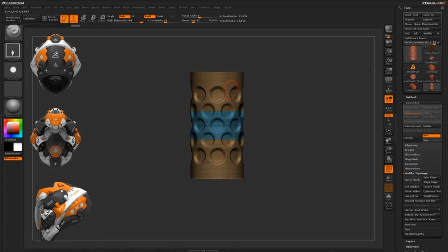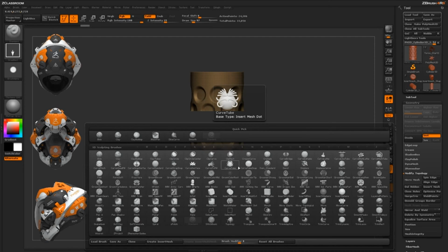And I want to go through and now generate 3 polygroups. So right now I have a polygroup here, but the top and the bottom polygroups are the same. So I need to set this bottom polygroup to be different from the one on the top. So I'm going to hold Control Shift and click and just isolate that bottom polygroup out. I'm going to hit B on my keyboard again, and locate the Select Rectangle.